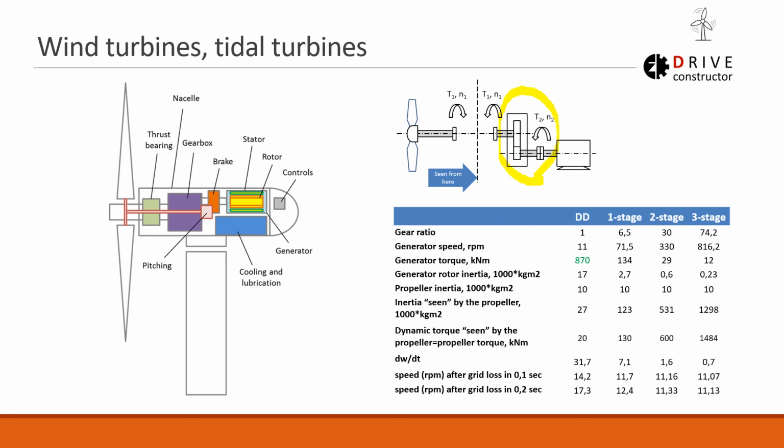In some other situation, in the winch situation, for example, if we are dragging a net behind the vessel and the net is stuck, then the gearbox can play a negative role. So it will sort of make the dynamics of the system slower, and you just break the winch or your wire collapses. So this situation should be analyzed with special expressions.